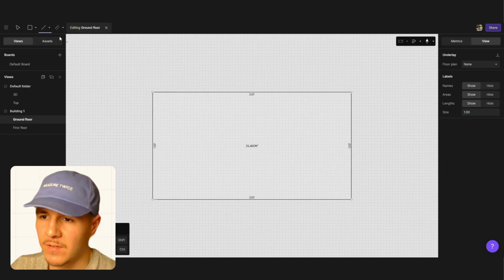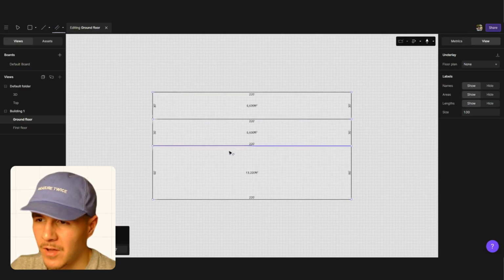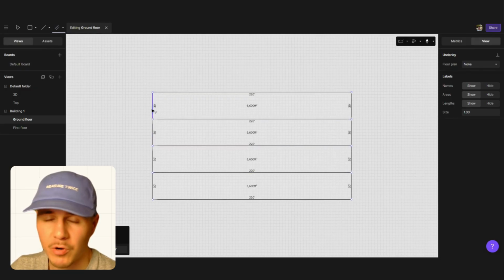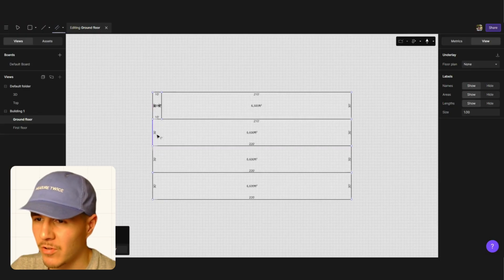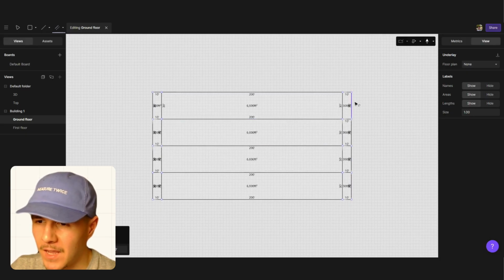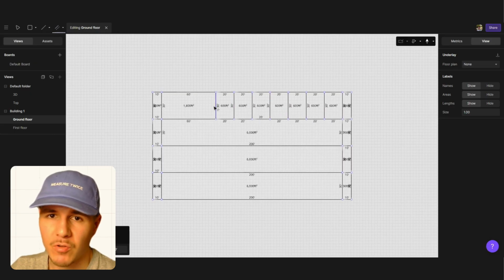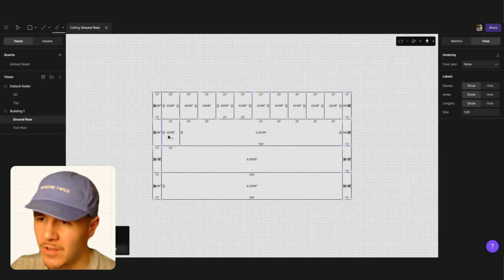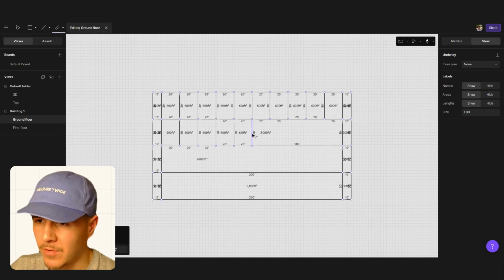Now, this is a pretty simple building, much simpler than the multiple floor buildings that I've done in the past. For this one, what I want to do is explore how to create a structure, how to set your structures within a project. The way to do that is basically I'm going to model what I did for the Nakagin Hotel Capsule Tower, and I'm going to create a grid. From that grid, I'm going to lay out my columns for the building itself.